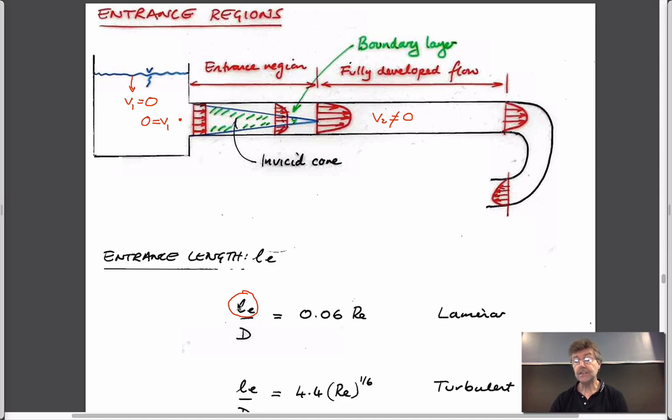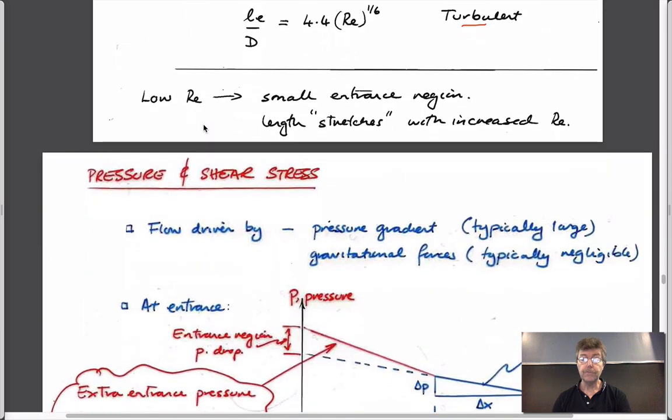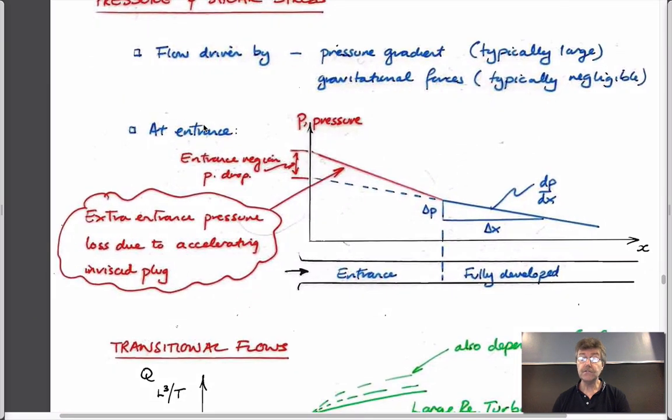And the lengths at which it takes to do that change whether you're looking at laminar flow or turbulent flow. And physically all you're doing is accelerating something from 0 velocity here to some finite velocity here, and to do that you have to apply some energy. So if you look, for instance, at the pressure drop along this pipe, you'd have to spend more energy to be able to get this moving. And we can calculate what those are also as a function of the stress regime.